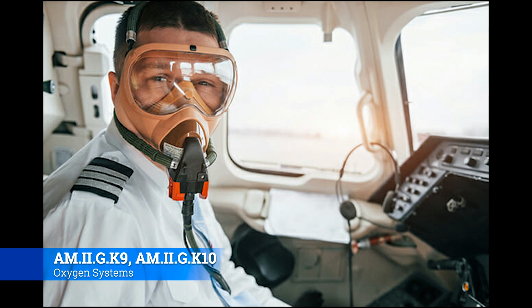What you'll do is put on a pair of gloves, like white oxygen gloves. You'll unroll the things that attach it to your head, the headbands, and you'll wipe out the interior of that mask, repack it per the AMM, put it back in there, and sign it off. And what that's doing is allowing you a chance to see and inspect and make sure that there are no holes or damage to the hoses, to the seal, or anything, and making sure that it's also still clean.